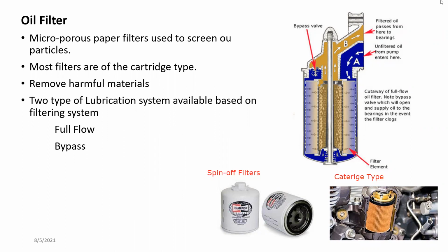Before I go there, I have to explain this. Usually, most people think lubricant is sent first through the middle of the filter and returned from the outside, but it's not the case. It's actually the other way around. Lubricant comes through the outside and then goes through to the inside.